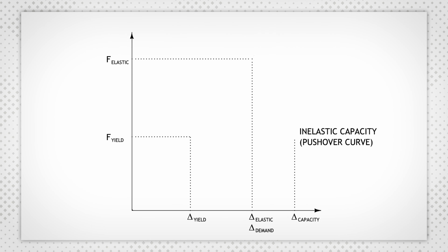In seismic analysis, it's not force-based, it's displacement-based, and the loads are applied differently. That same stiffness becomes an enemy of seismic design, because they want flexibility to allow the ductility of the steel, the yielding of the steel, to absorb the energy. Seismic is much more complicated.